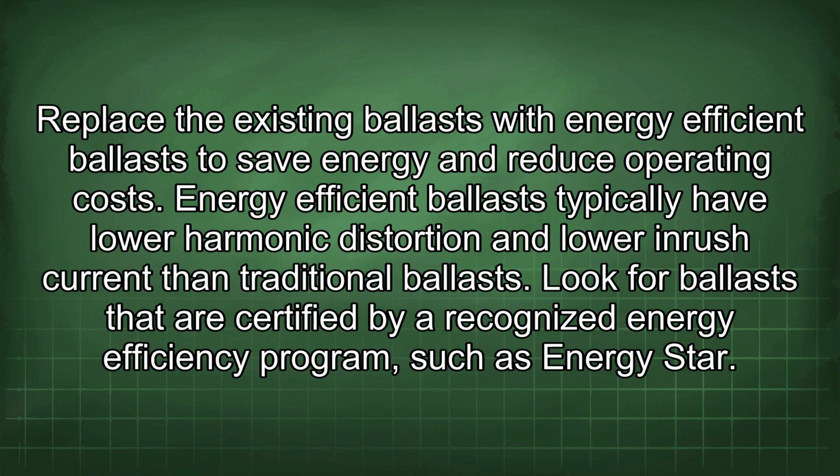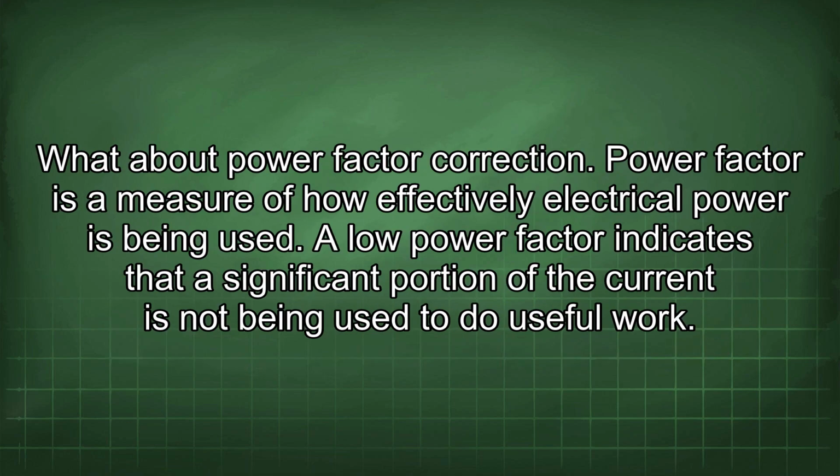Energy efficient ballasts typically have lower harmonic distortion and lower inrush current than traditional ballasts. Look for ballasts that are certified by a recognized energy efficiency program such as Energy Star. What about power factor correction?